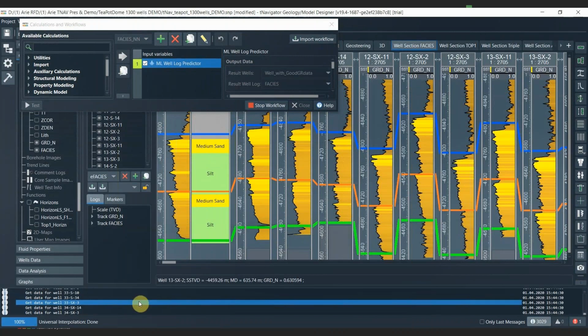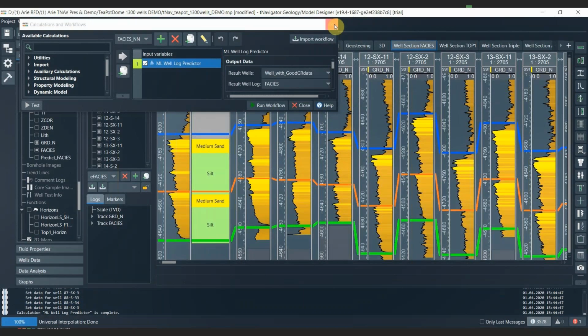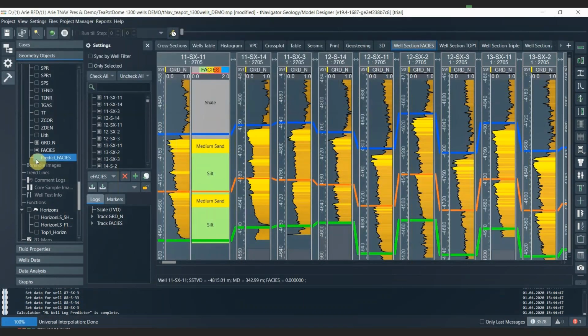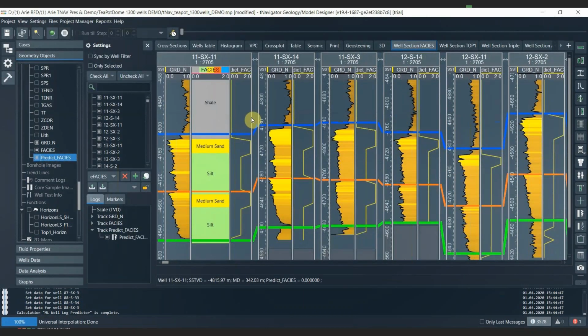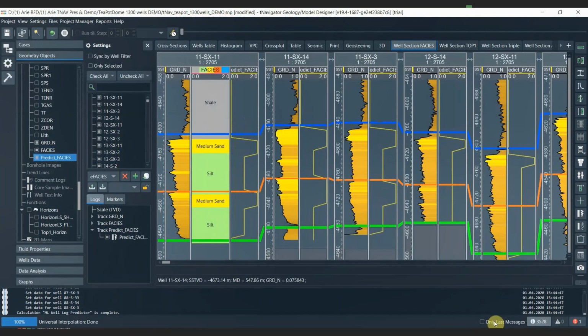So now the software will look at the entire field to see which wells have that gamma ray input, and then after it has all that information, it will train. Based on our initial interpretation, it can train the software to recognize where the potential max sand is in all the other wells. So you can see here, that's my new interpretation based on my neural network.